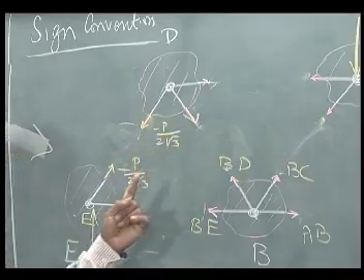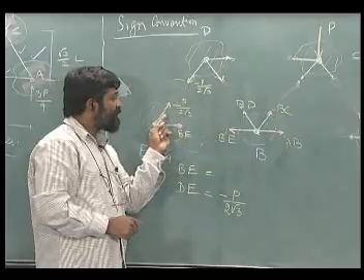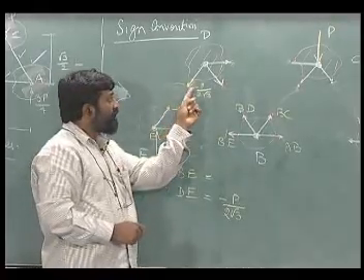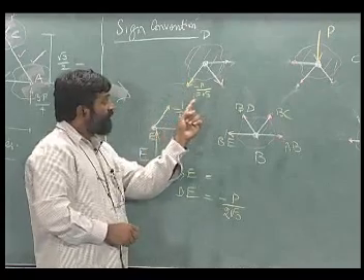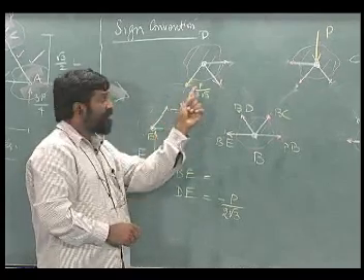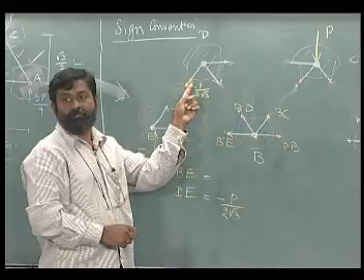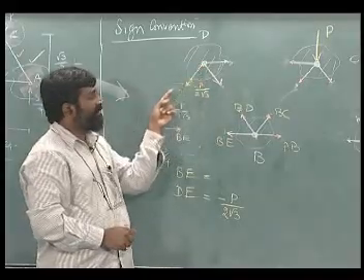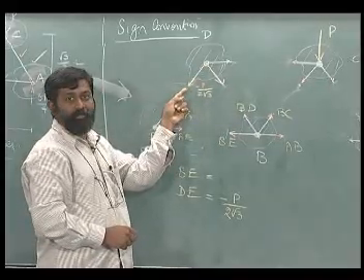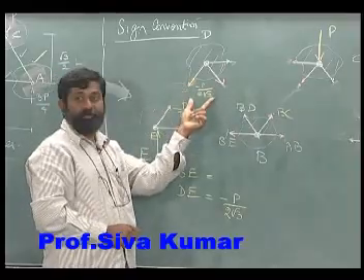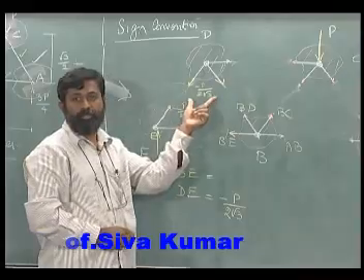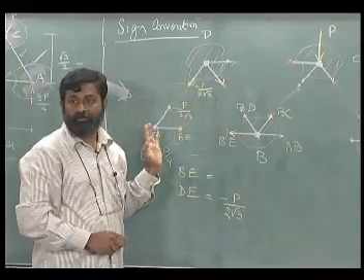One of the common mistakes done by people is, since this direction is minus, this should be plus. No, this is an internal force. If I got this as minus, this also should be equal to minus. When I solve at D, this particular direction is taken as it is, and the magnitude is taken as minus P by 2 root 3. This is important to note.